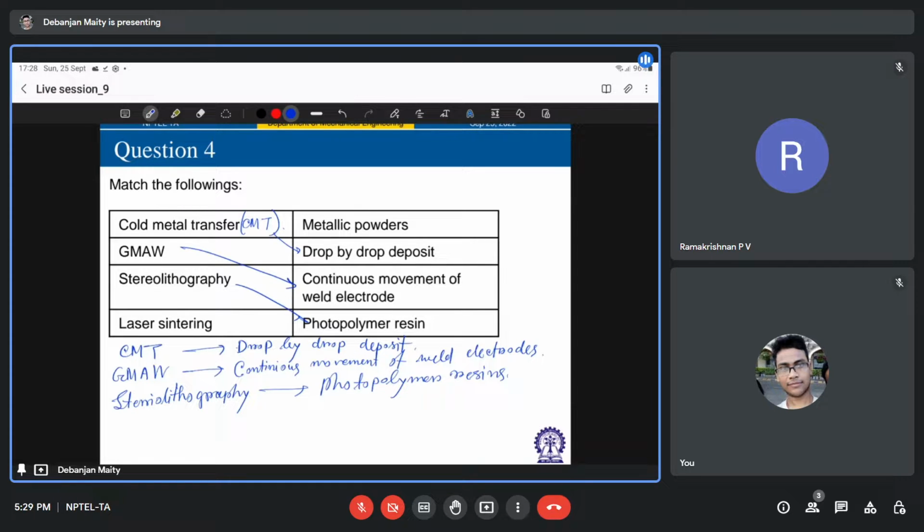Now, laser sintering can be used with polyamide, or maybe titanium and rubber-like materials. The laser basically fuses powders while the rest remain as loose powders. After you melt one layer, a new layer of fresh powder is spread over the surface by a roller. Mainly, no support structure is required, and the unsintered powder is used as a support material in laser sintering.